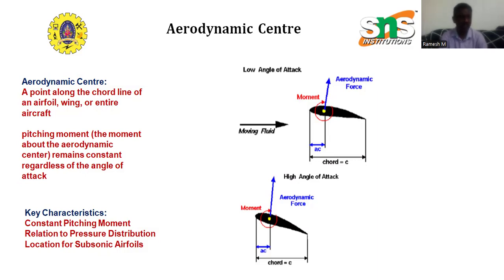We call the average location of the pressure variation the center of pressure, in the same way that we call the average location of the weight of an object the center of gravity. In general, the pressure distribution around the object also imparts a torque or moment on the object. If a flying airfoil is not constrained in some way, it will flip as it moves through the air.